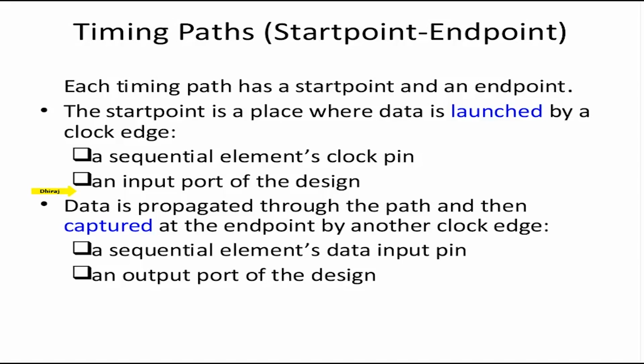The aim of synthesis in Design Compiler is to fix performance issues, to convert RTL into gates such that it meets the performance, that is, the clock frequency criteria. This criteria is represented by the setup time equation.